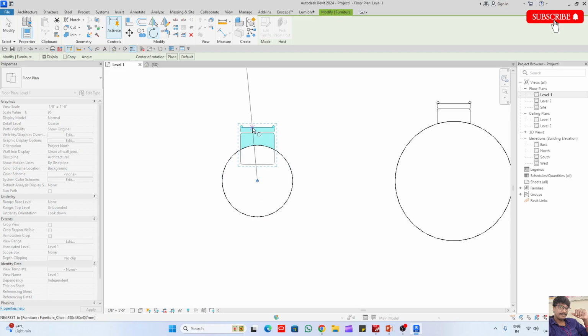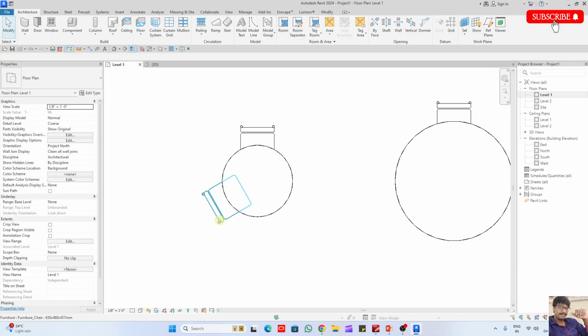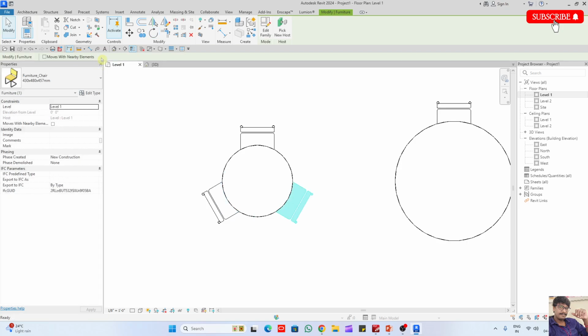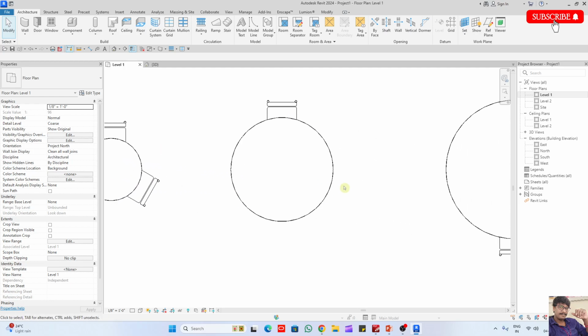First select the object, RO, specify the center of rotation. I specified, and then turn on copy, specify the angle. How much angle? 120, enter. Now select the object, rotate, place, click on the object point you want to take as reference, and then copy. How much angle? Done.